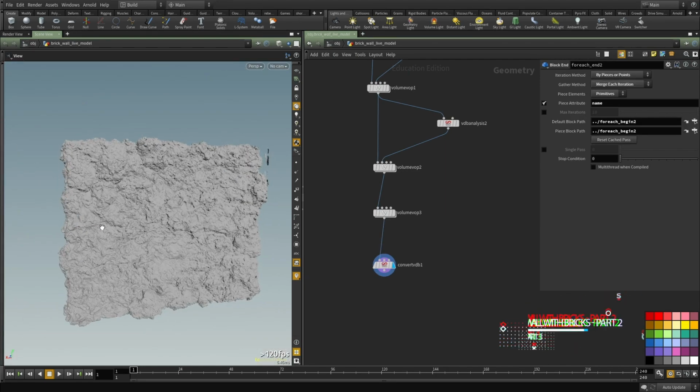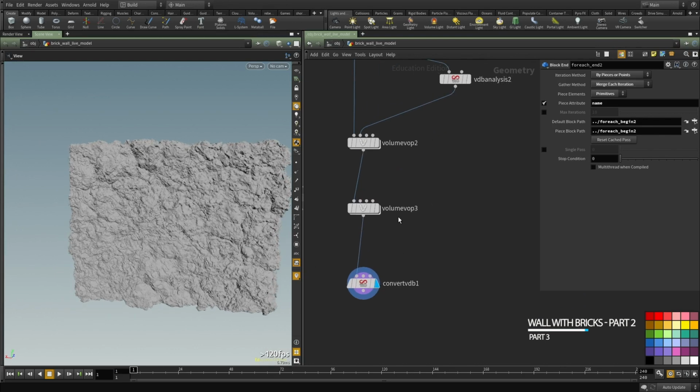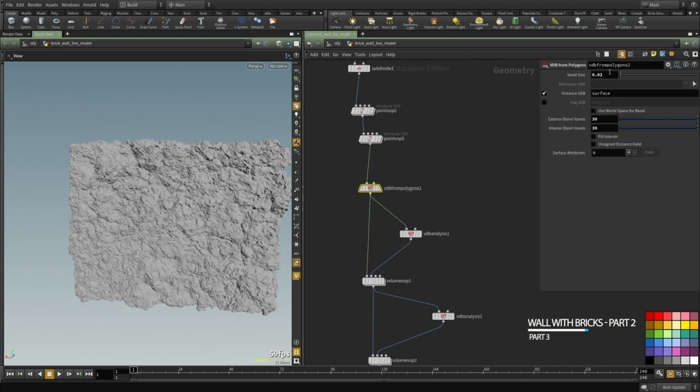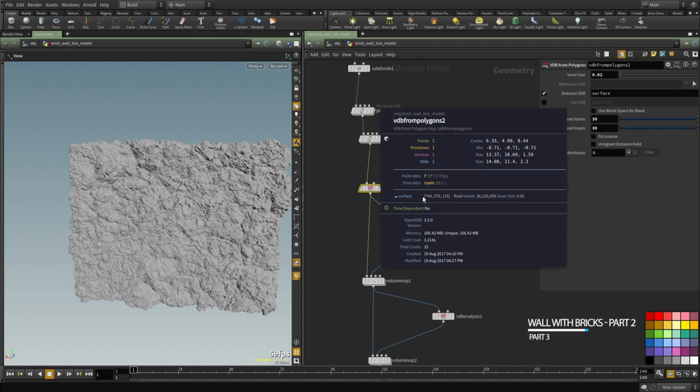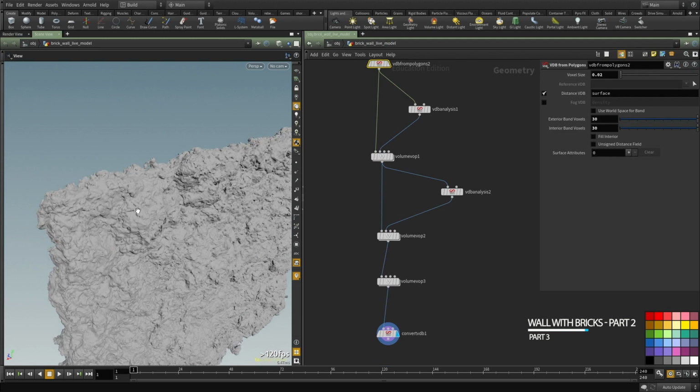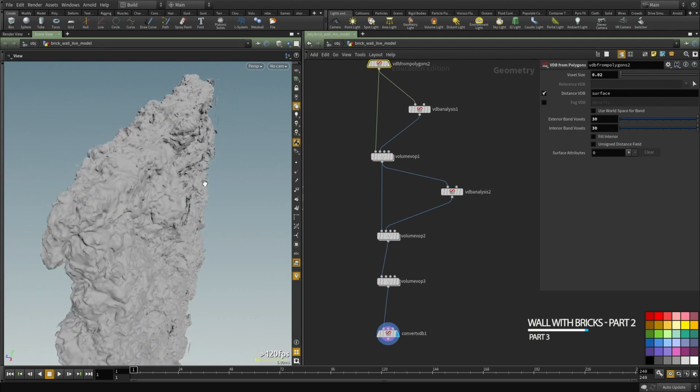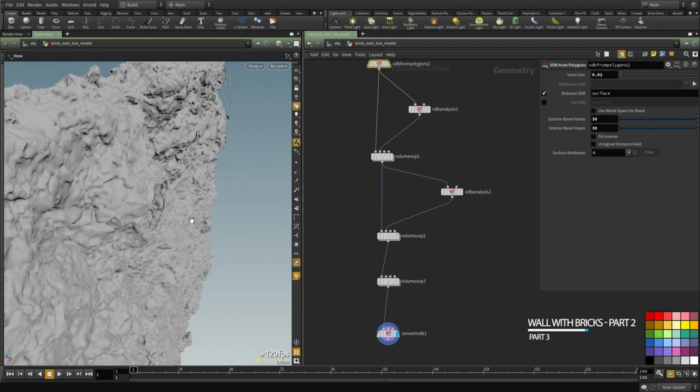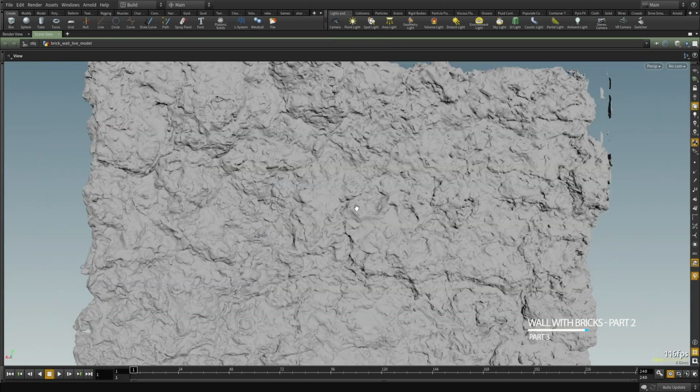So now I've waited for this. It took, I think, 2 minutes, and I lowered the resolution a bit, so it's 0.02, so it's this much, and I expanded these guys a little bit more because I saw some clipping and it's still there. I need to expand it a little bit so it doesn't run into this issue. But this is the final mesh.